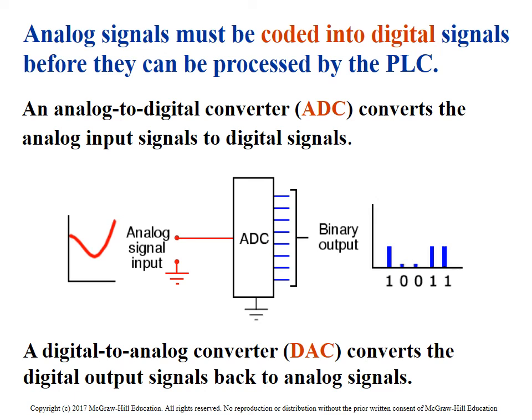That's really what this ADC is doing. It's taking some analog signal, say it's getting some value, say 256 or 300 or 500, and it's converting that into a series of ones and zeros that the PLC can understand. That's really all it does.